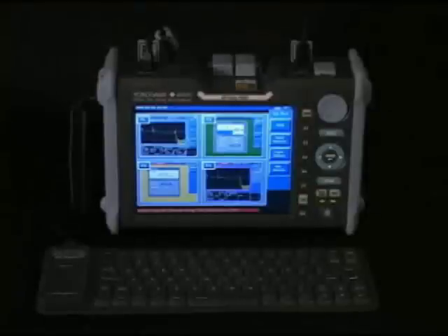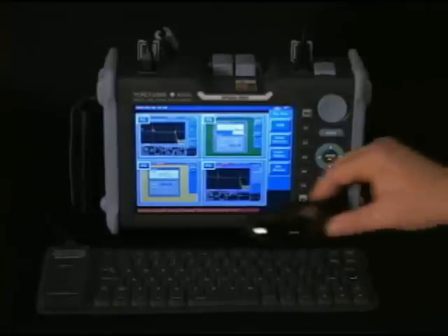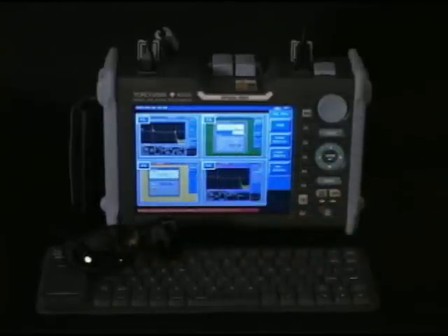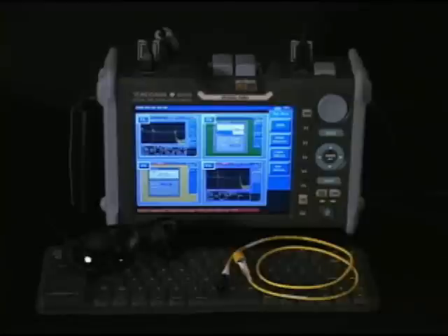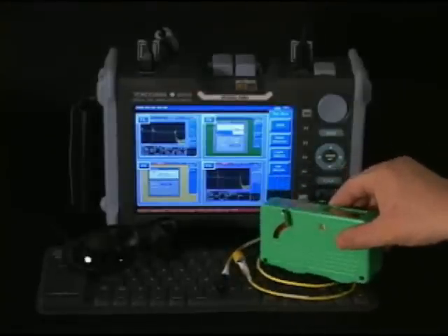Before we begin using the OTDR, let's have a brief word about safety. Never look directly into a fiber or laser source. Be sure to have a fiber connected to the OTDR prior to using the average or real-time keys. Check the fiber to be tested for live signals. You may be required to wear some level of eye protection as defined by your company. Always attach covers on fibers not in use. This keeps them clean and protected against accidental exposure. Also, to prevent damage to the optics, always be sure to clean your fibers prior to connecting them.